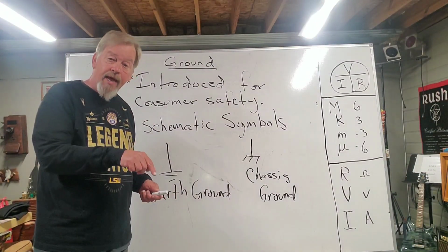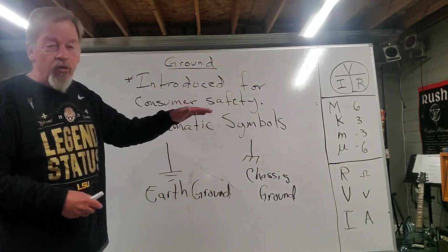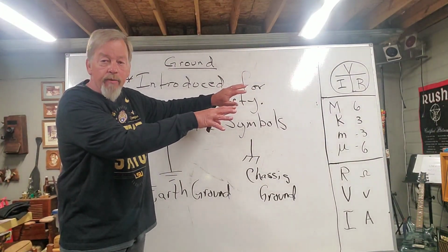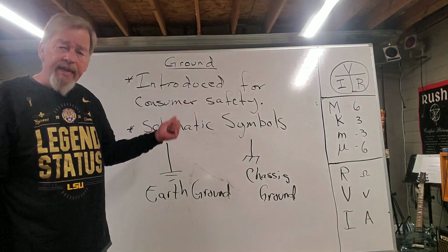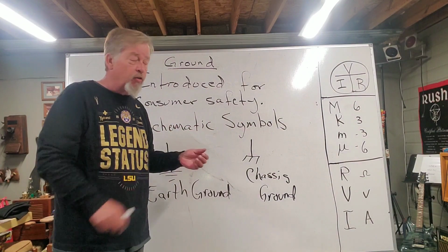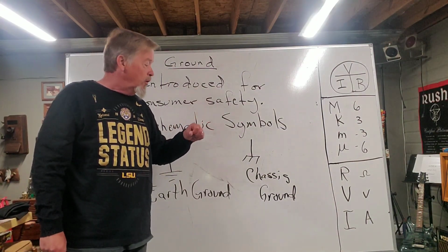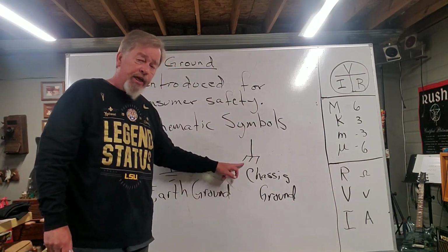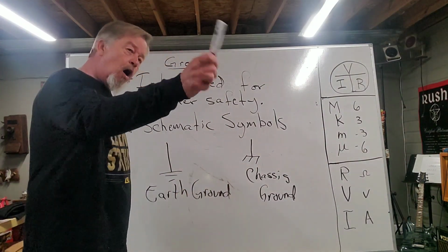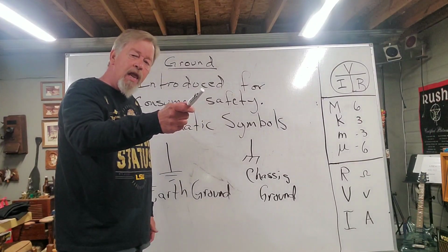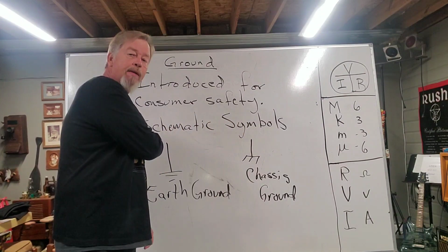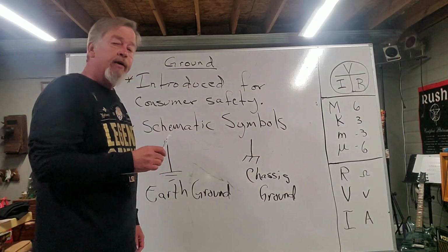Well, the red side of the battery connects to a fuse box where all your different circuits are distributed. Tail lights, headlights, every part in the car that's fused up. And so, if you think about it, the manufacturer will run a wire all the way back to that back tail light, but do you think they're going to spend the money to run that wire all the way back to the battery? They're not going to do that.